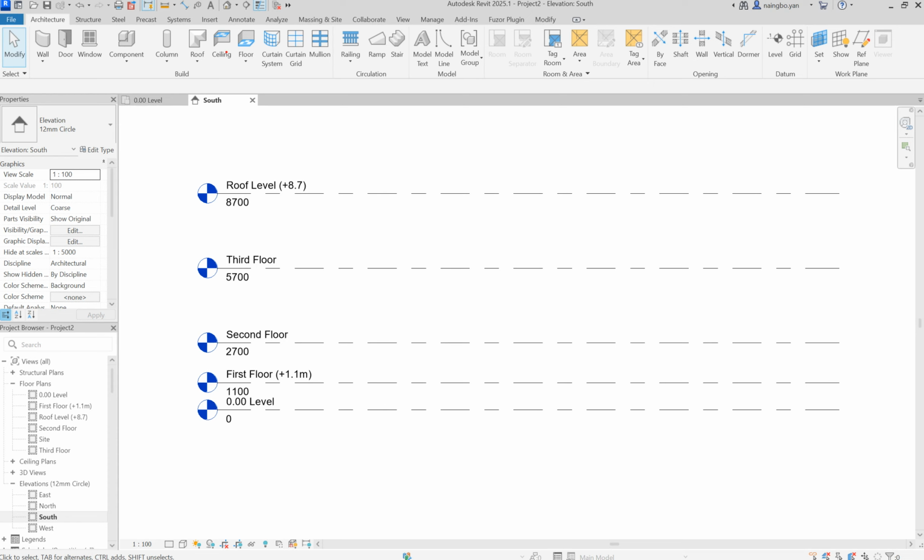So I will click to this 3D view, or you can go to the View tab and 3D view. Anyway, you can see 3D, and here I just right-click and zoom to fit, but I don't see any levels. So what I can do is show you VV, visibility graphics, because I want to go to the annotation and see that all these levels are on.